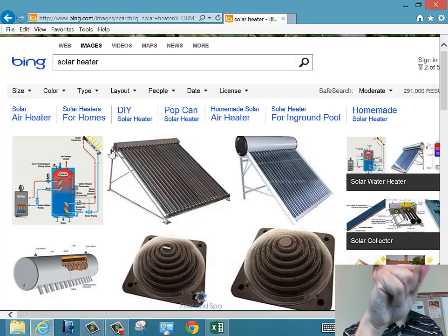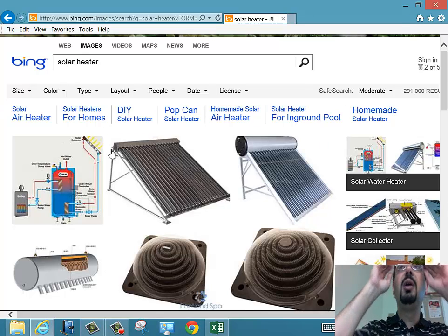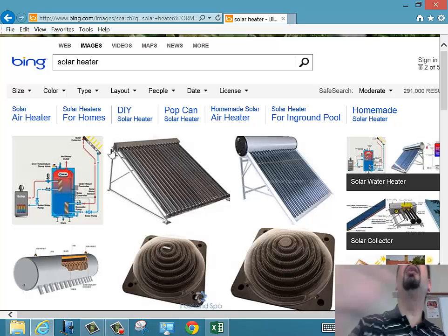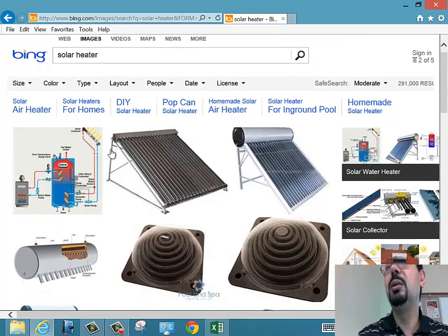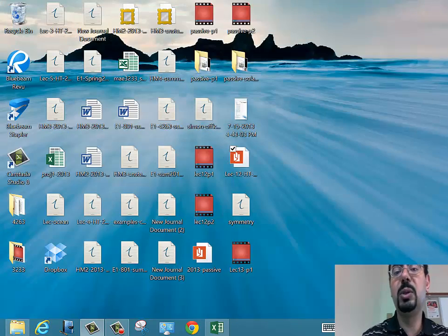They will claim this, of course, in their brochure, and they will tell you, our solar heater can beat any other solar heater in competition because we use selective coating, where epsilon is really small and alpha is really, really high. So we absorb, but we don't radiate. And so this surface gets hotter and hotter without losing radiation to the outside.